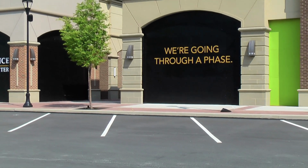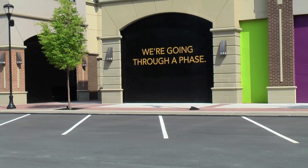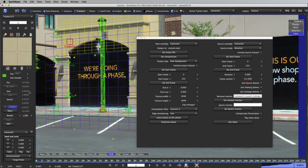As in our initial tutorial using splines, at this point, ignoring the little base and the stuff way up at the top, the thing that you see most now is the difference in intensity level between the part that we are transferring and the part that isn't. So again, we can do the illumination compensation. And if you look over here, you'll see that there's a supervised tracker that I set up earlier, and it's actually an offset tracker. So the underlying tracker is down here, but I've moved it up and expanded it so that it's sitting on that facing wall. That's the thing that we want to have match up.